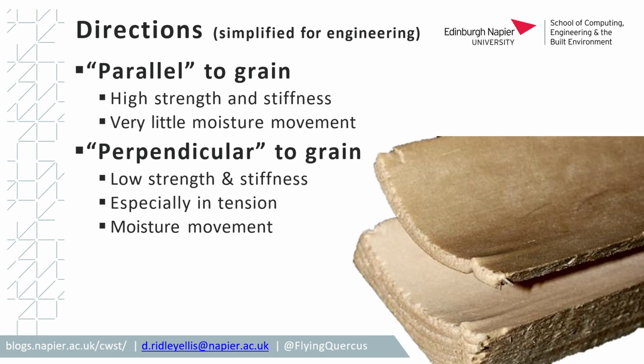So for engineering, we don't want to get too particular, but it's only people like Dan Ellis and Wojciech, who most of you have met, who get very caught up in the much more finite detail. But for engineers, we just need to know parallel to grain, perpendicular to grain, and the load properties are incredibly different.